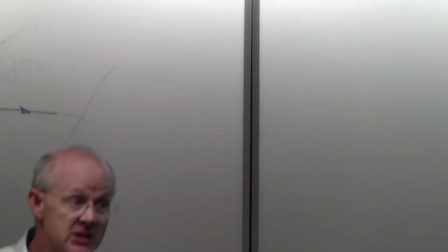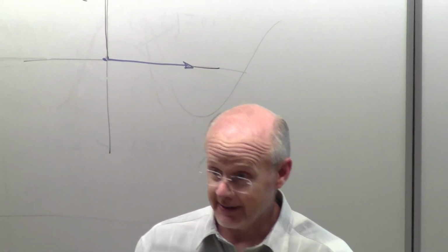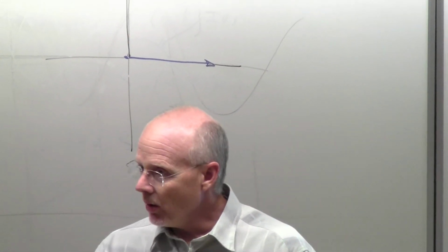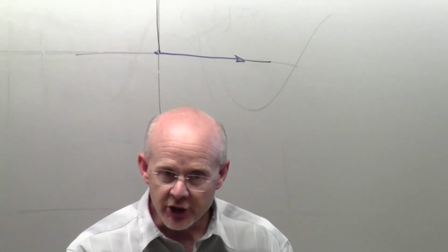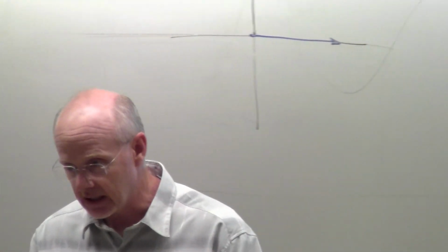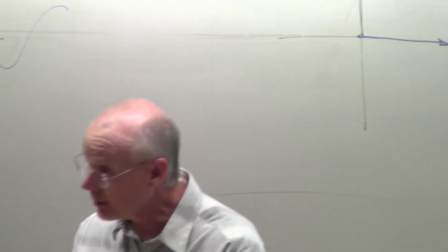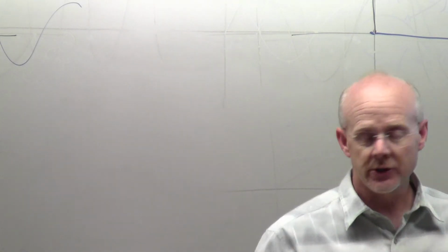Now you can see this is getting pretty ugly looking here with all these voltages, right? So I'm hoping it'll look a lot easier when I do my phasors. And it will. I've got three trig functions to add together, right? Four to visualize, three to add together. I've got to add the voltages. I'm not going to add current to voltage. That doesn't make any sense. But I've got to add the voltage of the inductor, the voltage of the capacitor, and the voltage of the resistor.